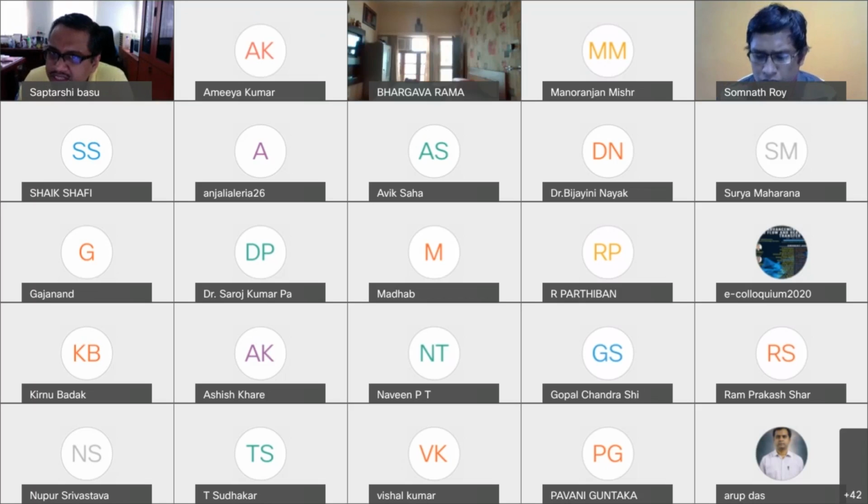We checked whether there really is a variation or not. We validated both of those, and then came up with the actual surface tension gradient, the actual deficit in surface tension, and then used it to calculate the Marangoni scale. The Marangoni scale is just a scale, not an exact value. The exact value comes, of course, from the measurements.